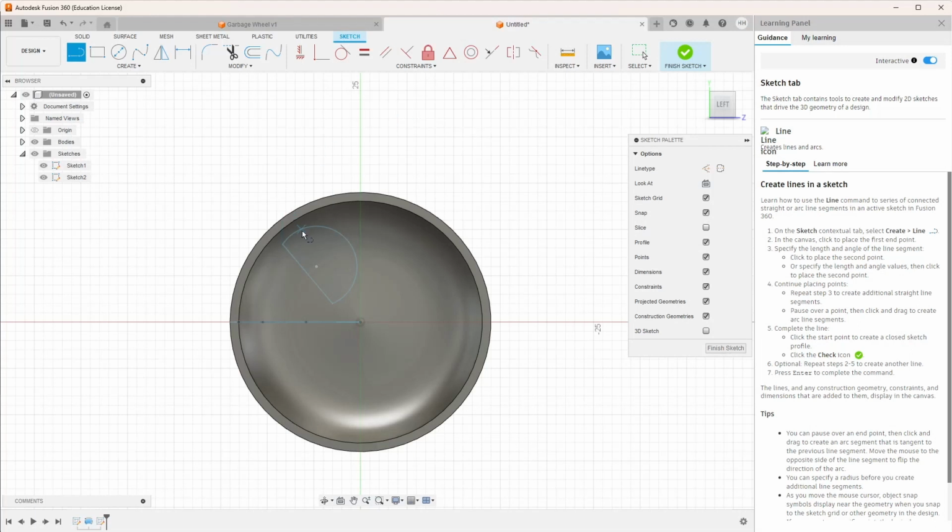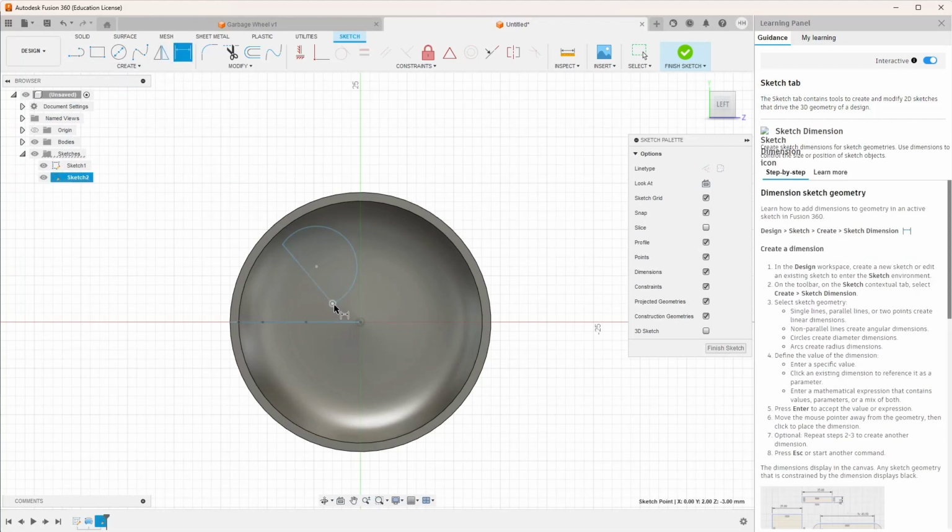And there's ways to locate that shape like that. And let's say we don't really like the location of it, the distance between here and here, so we change that to 4. It would move the shape. But I actually think it needs to go more that way. So instead of 4, let's use 2.5. Okay, that's looking a little bit better. And this shape is something I'm going to cut out to remove material.